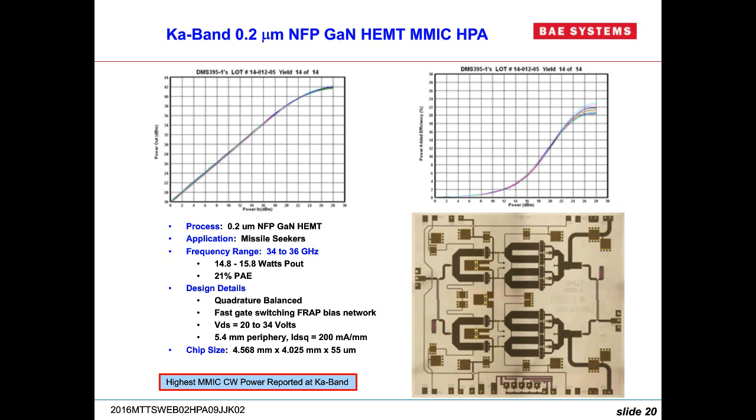Now, that's my personal opinion. There are efforts out there that are funded to develop things in silicon, such as phased arrays, but if you artificially force functions into it, you may need a 10,000 element silicon array to reach the same level of performance of a GaN pHEMT front end phased array with a silicon back end in terms of cost and performance. And I'm not sure that 10,000 elements is going to get you to the same cost as 100 elements using more exotic semiconductor technologies.